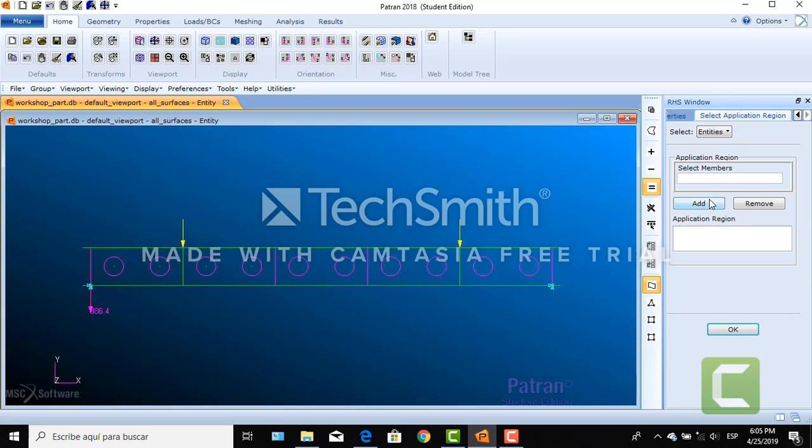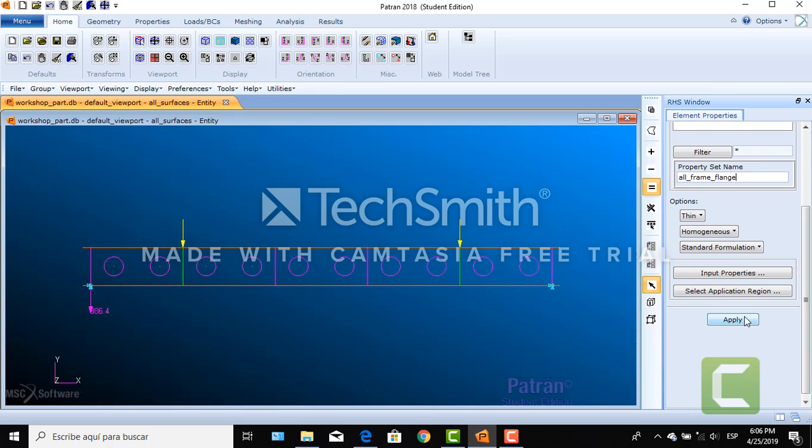We're gonna close it, and in the select members, we're gonna choose only the top and bottom flanges. So we're gonna go like this, very careful. There we selected the top part, and now we select the bottom part of it by holding shift. I forgot to hold shift there, so there you go. So we click on add, we select OK, and we apply those.